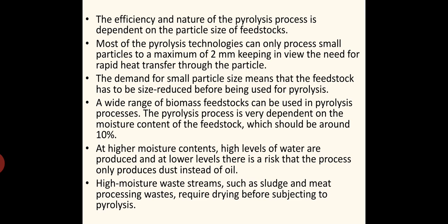So there is a pre-requirement for the process of pyrolysis, or heating is initially done for the feedstock before going for the pyrolysis process. At higher moisture contents, high levels of water are produced, and at lower levels, there is a risk that the process only produces dust instead of oil. So if the moisture content is more, high levels of water are produced during pyrolysis, and if the moisture content is less than 10%, then instead of getting oil as the byproduct, we will get completely burnt dust only.